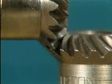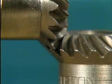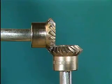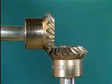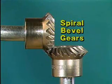This design increases the surface area of the teeth and allows the teeth to engage more gradually. Since the teeth engage gradually, the noise produced by the gear set is reduced, and since the gear teeth are twisted, more gear teeth can be meshed at the same time. This increases the load that the gear set can transmit. Bevel gears made this way are called spiral bevel gears.